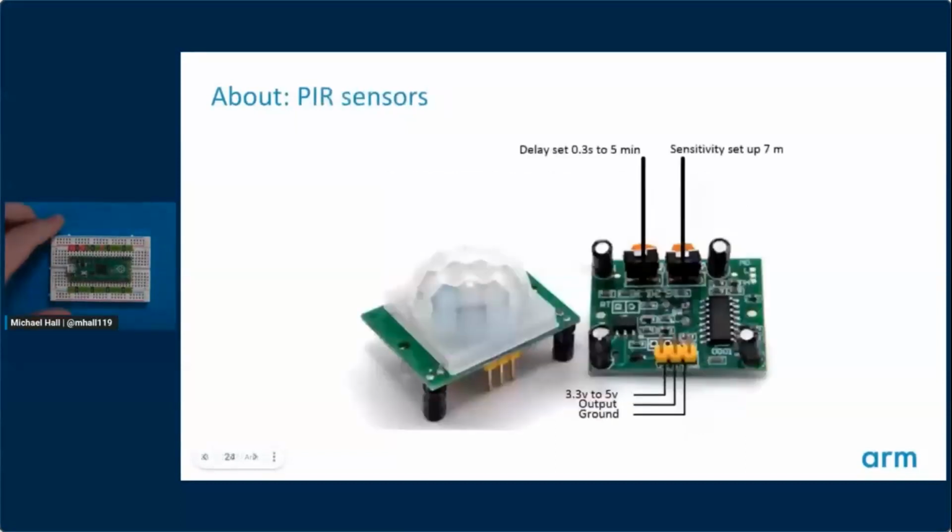We are also going to be using a couple of sensors. The first one is going to be this PIR sensor. It's a passive infrared sensor. This is used in most motion detection applications because it's really cheap, it's really effective. Basically, it's going to see infrared photons coming off of a moving body, and it's going to trigger based on that. There are some controls here that you can use to adjust the sensitivity and the timing of that. We're just going to leave ours turned way down for this demo because we're not building an actual prototype device.